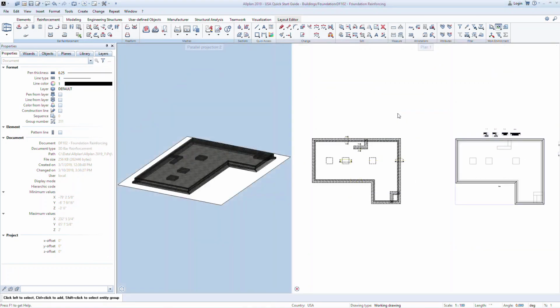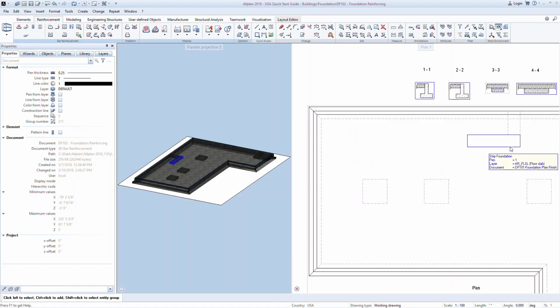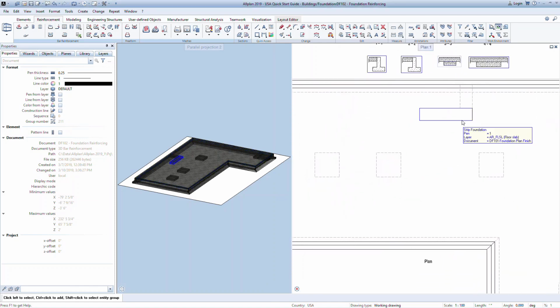In Allplan, we use the sections and views to model reinforcement, and we will see this generates the 3D rebar automatically. Zoom into the plan view and sections that have been created. We'll start by reinforcing the spread footing under a column to show how quick and easy the area reinforcement command can be. The center footing is represented by section 44. Again, we can confirm this by hovering over the footing and seeing it highlighted in all sections.